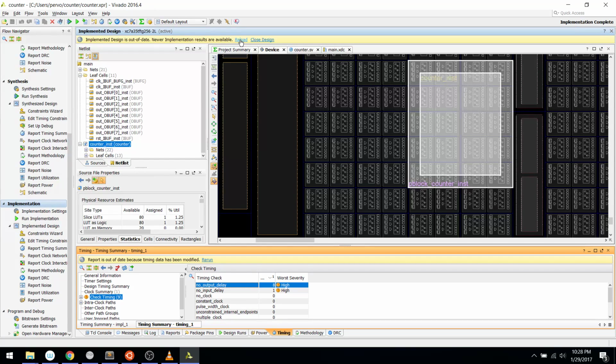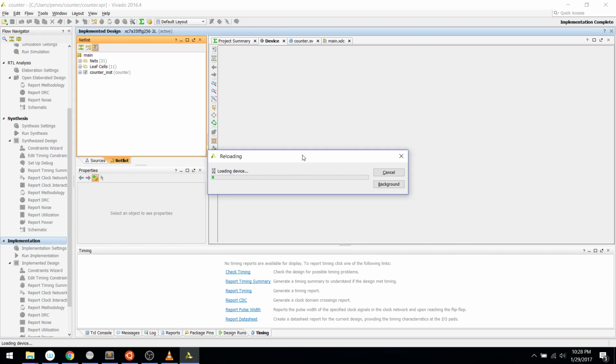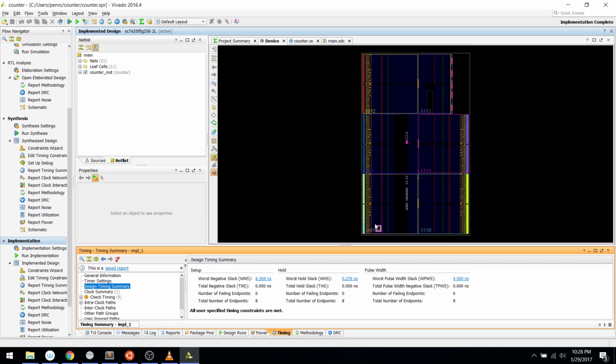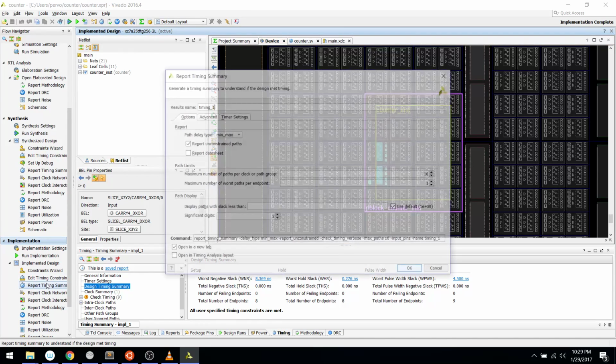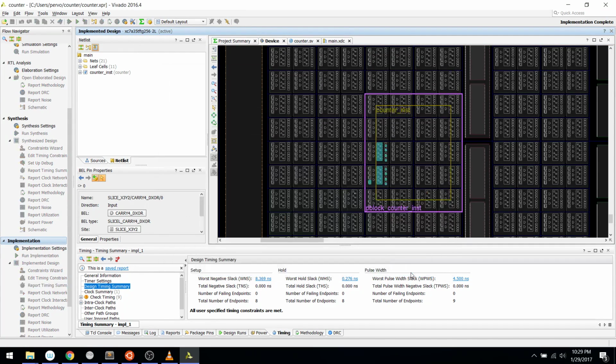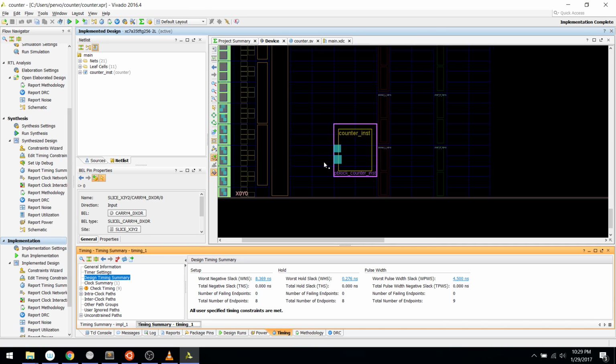All right, so we just reloaded this. Let's see if it actually met our P-block constraint. I believe it did. You can see here, it now placed stuff within the block, but still to the leftmost edge because it wants to be close to stuff. If we rerun our timing report, maybe the delay isn't noticeably longer, but let's check. Yeah, so it looks like this is already updated. Okay, I guess the distance is not a big issue for this.